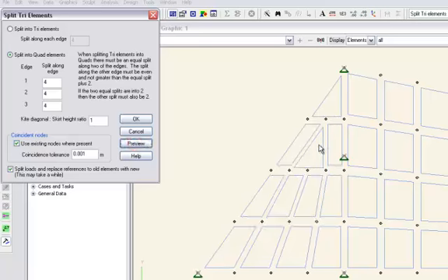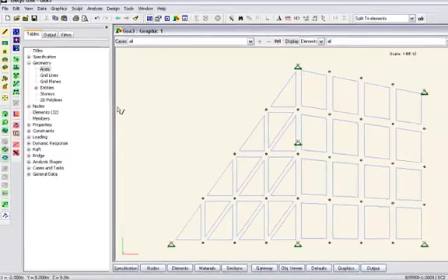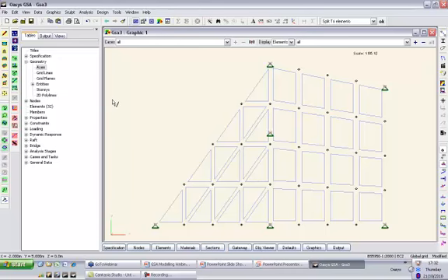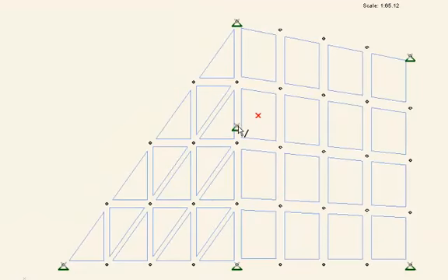So at the top they're actually quads, and they will throw up quite an error if you try to analyze those. So let's keep them as triangles. Now, in this case, we could analyze this, but this node is not really attached and it's not quite matching in. I mean, we could drag the node onto there, and so on. That's not very satisfactory. So this is where auto meshing will come in, which I'll come back to in a moment.